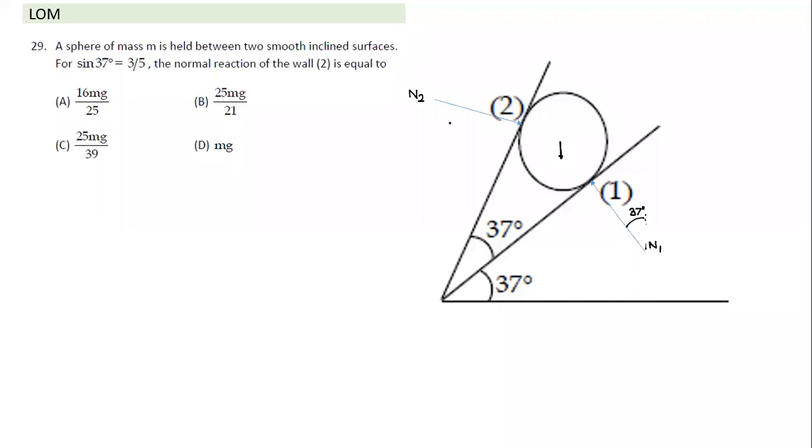That's where Vignesh, you said you had a little problem. So this angle is of course 74. The total angle is 90, so this angle has to be 16 degree. So we understood the orientation of all three forces. This is vertical. This is making a 37 degree anti-clockwise with upward vertical. And this one is making an angle of 60 degree down from the horizontal.